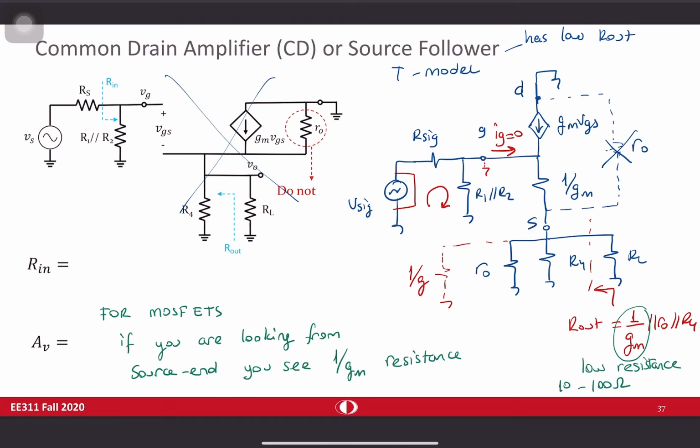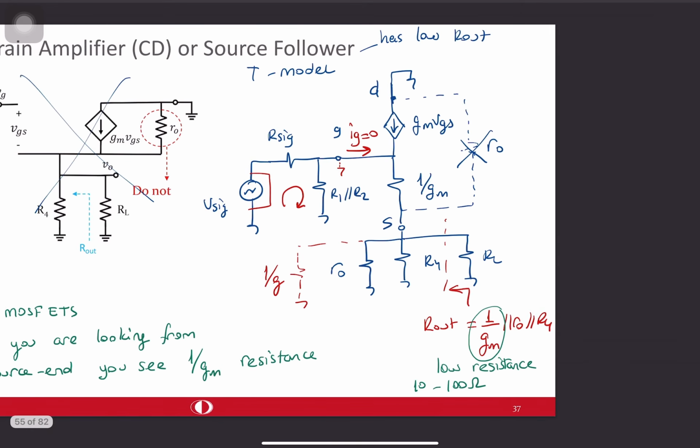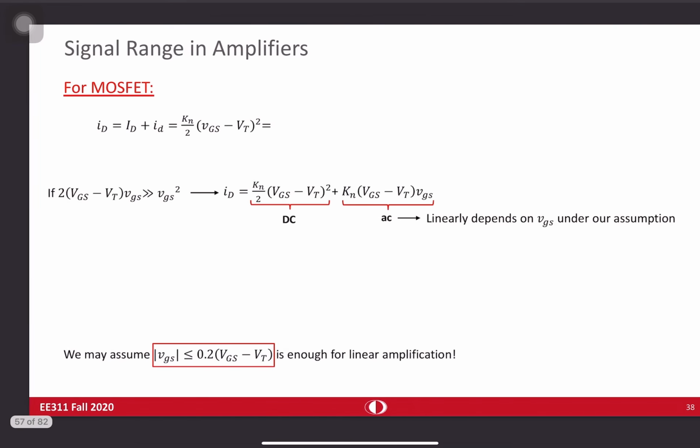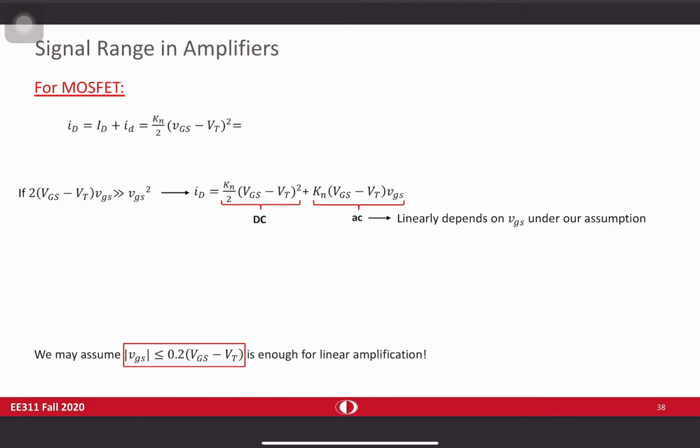Okay, so with this discussion, we complete the last type of single transistor MOS amplifiers. As you see, common gate is a good current buffer. Common drain is a good voltage buffer. With common source and common source with degeneration, you achieve the voltage gain which is required. And eventually, we are going to combine them, make multi-stage amplifiers to achieve all the good things in a single amplifier. But before then, let's discuss one thing that we haven't before.